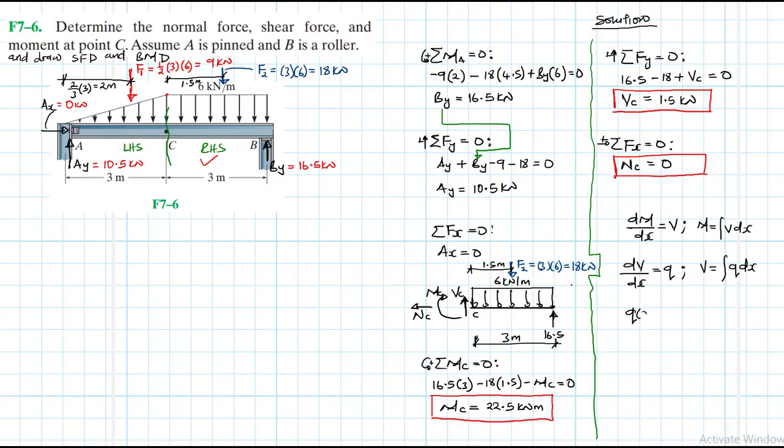If we have the distributed force as a function of x, written as, let's say, coefficient a, x to the power n, plus other factors that are not written down, and that function governs the distributed force, then you expect the function that governs shear to be equal to b x to the power n plus 1.